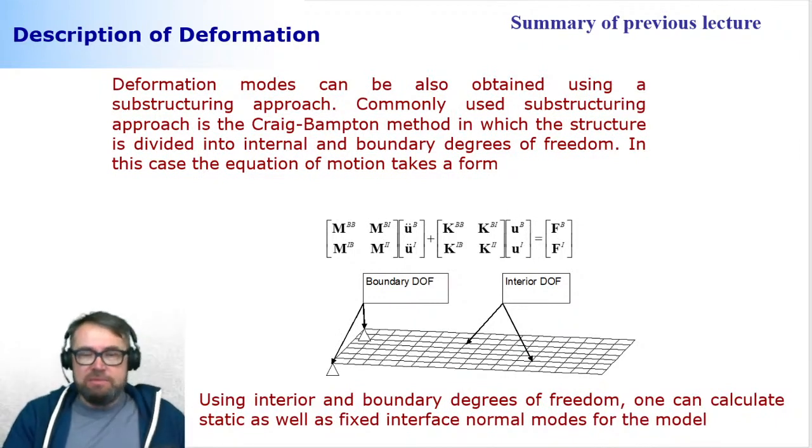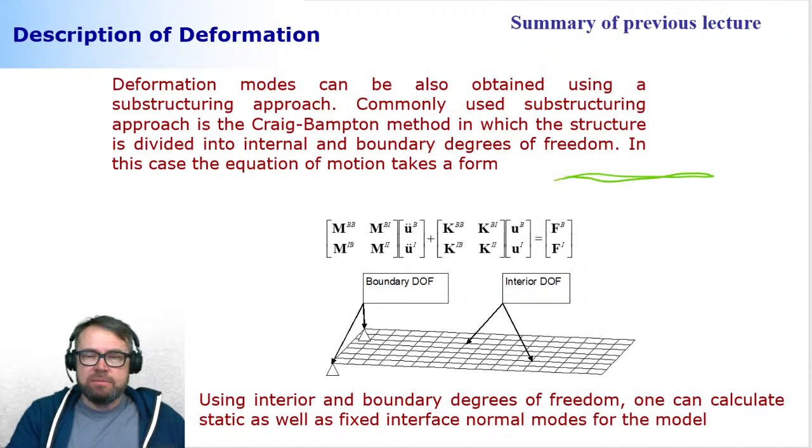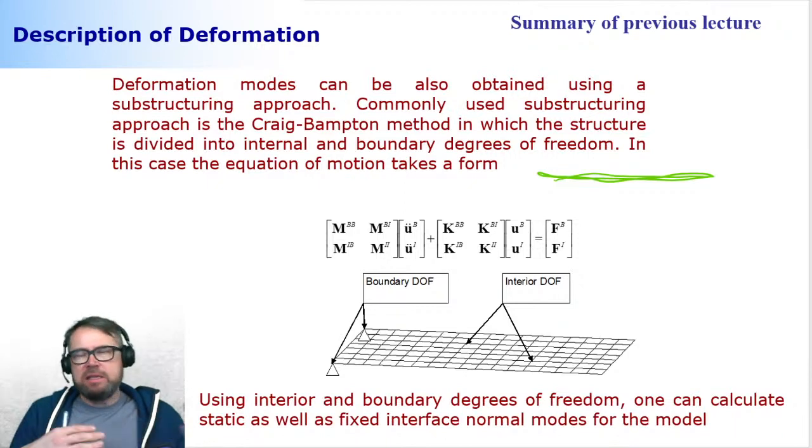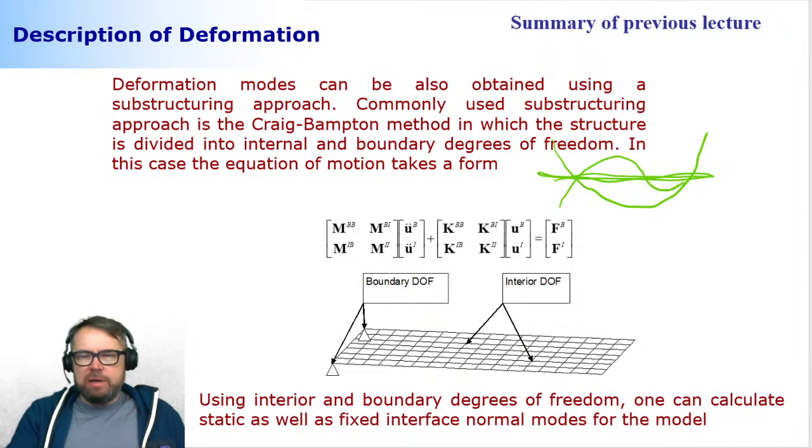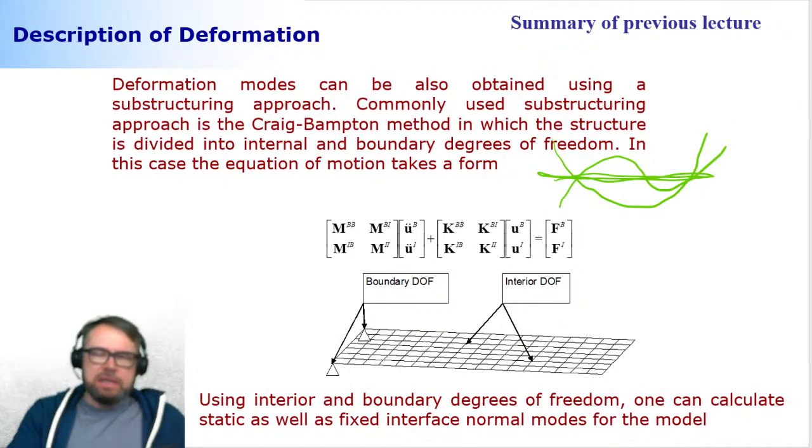If you deal with a beam-like structure, you put it in space and then conduct the eigenvalue analysis. You get these free modes. The first one will be something like a banana mode, the second more complicated like this, and so on and so forth. So you get a lot of modes. This is one way to create them.